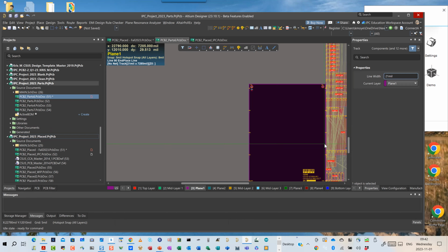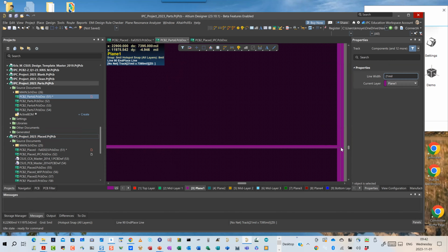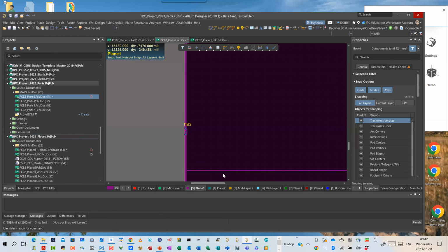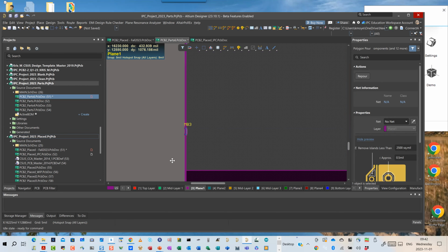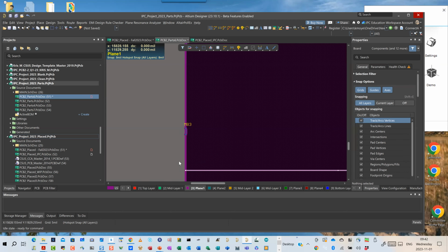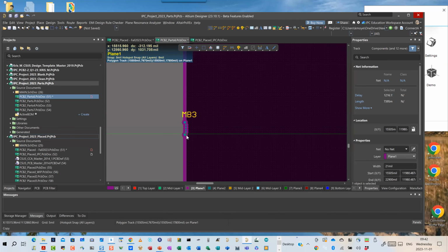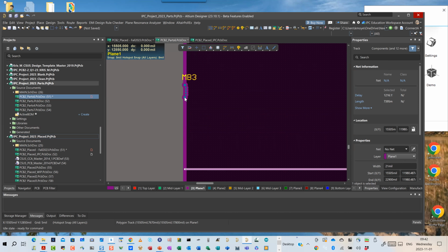And for now, I am literally going to draw that line right over to here. Okay. I'm then going to come in here and select that line, and I'm going to do a copy of that line. That's going to ask me for a reference point. I may pick the midpoint of that hole in my what I call my mouse bite. I'll explain mouse bites later when we get to documentation. But I'll put it in that centroid location right there.